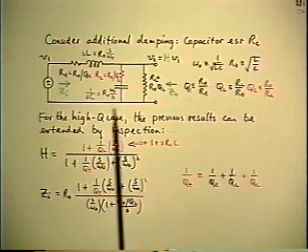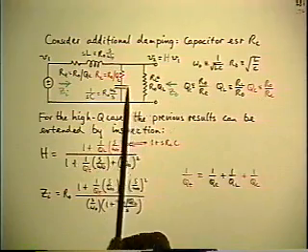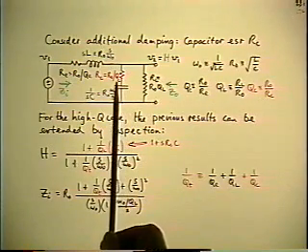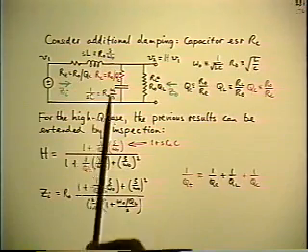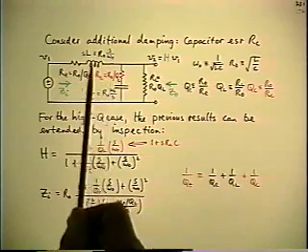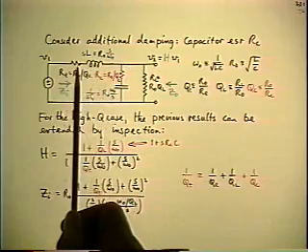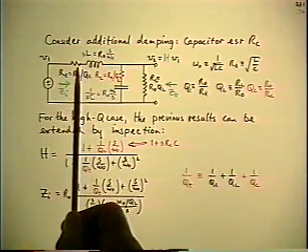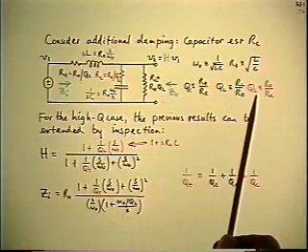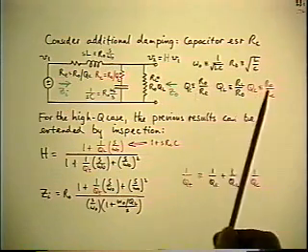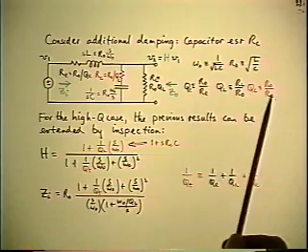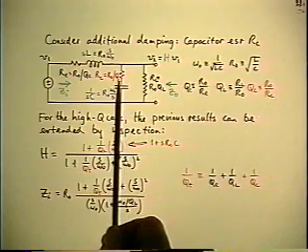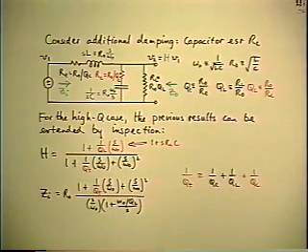And the answer to that question is it depends on what is the position of this resistor relative to the LC tank. And you see that it's in a series position relative to the LC, just like the RE was. So the appropriate way to define the QC is the same way up as the QE. Infinite QC will occur when RC goes to 0, which takes you back to the previous case.